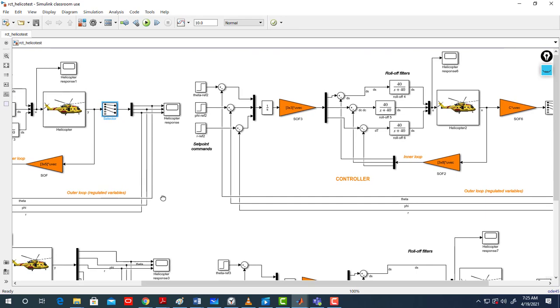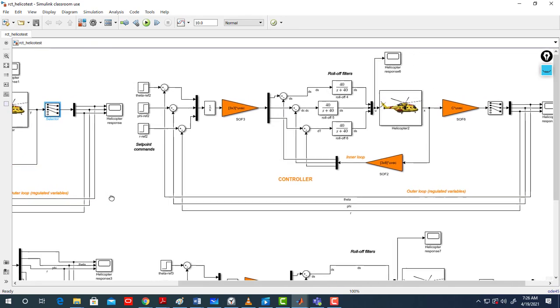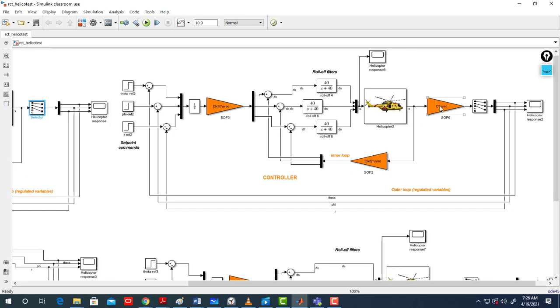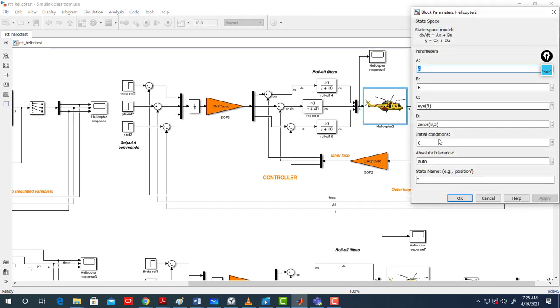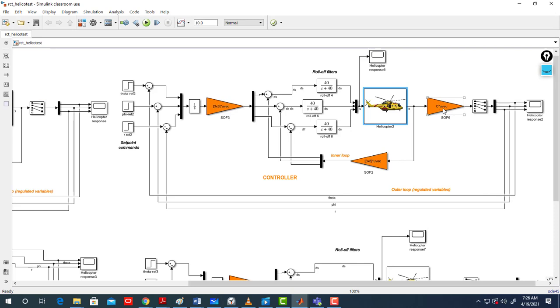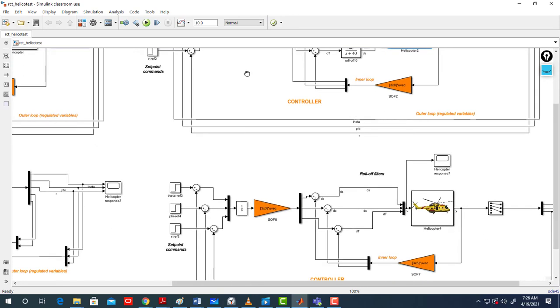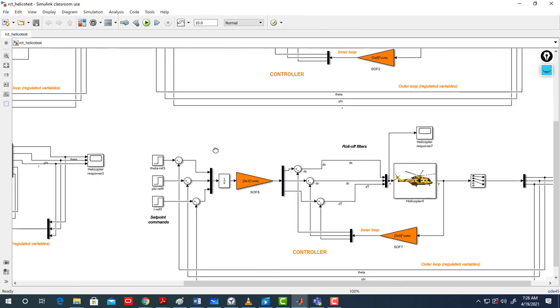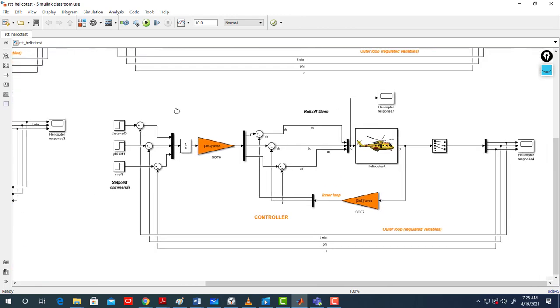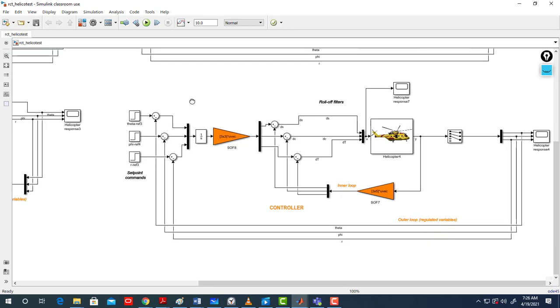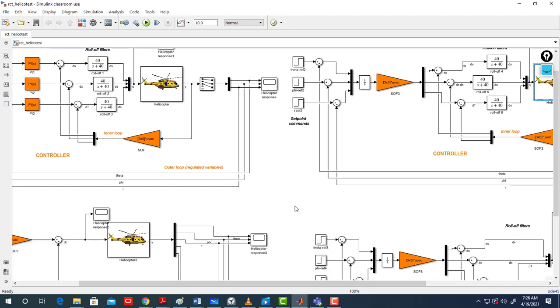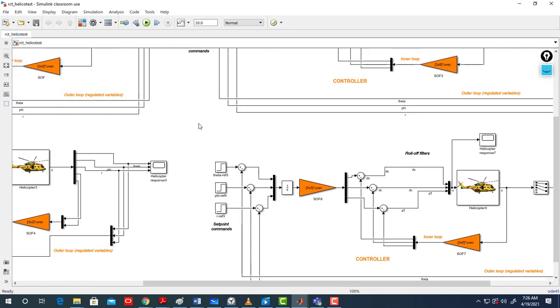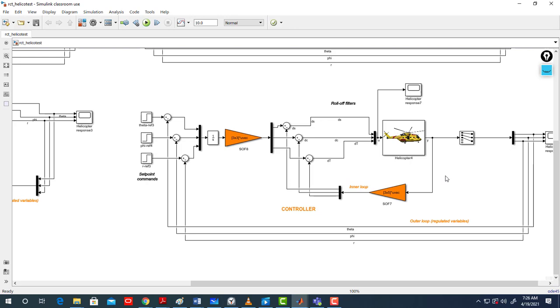So what we did is differently, as we studied in the lecture: we feed all the states, and so to feed all the states, I should have an identity matrix here. Therefore, I multiply by C to get the output and select the first 3 of them, I feed them back to here, and 1 over s because I'm an integrator. All of this we did last time, and we checked that if we don't use the rate filter in simulation, this doesn't affect your results, remember? But here we did it as in the tutorial, for the sake of comparison, and we get the same results almost everywhere.